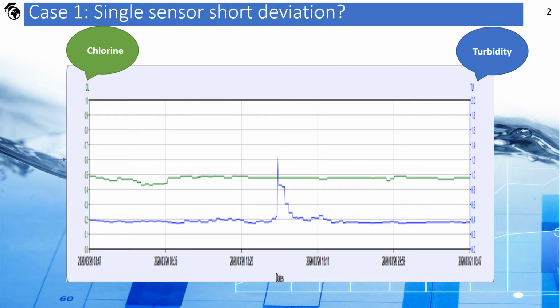This signal indicates that this is not an electrical problem. In most cases, this signal is a result of a small amount of dirt at the measuring chamber. There was no violation of user limits, which indicates that the amount of affecting substance is low.